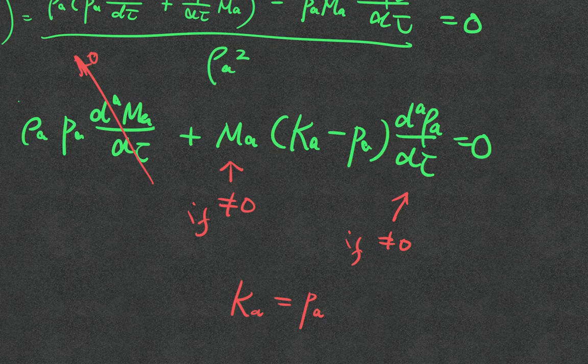If you want to simulate an explosive, that definitely won't work, okay? Because you have to consider the temperature. And you may also not have a linear relationship that you can describe in terms of one single bulk modulus for the volumetric response. Now this is a big assumption, but in some cases, this is actually what we use.